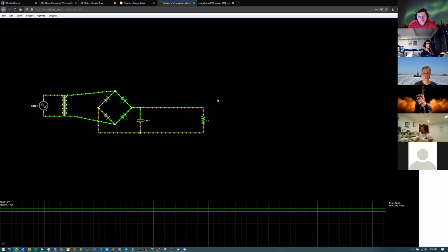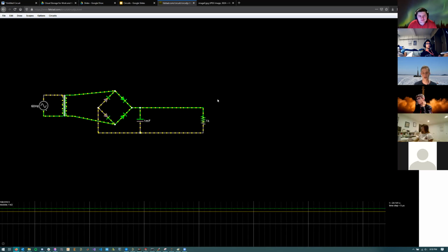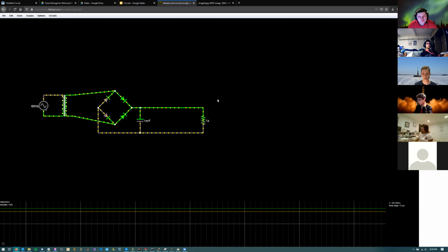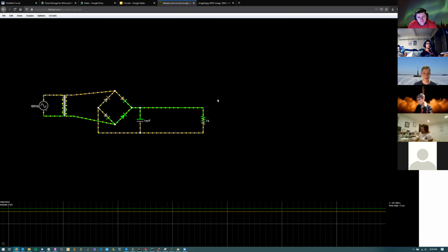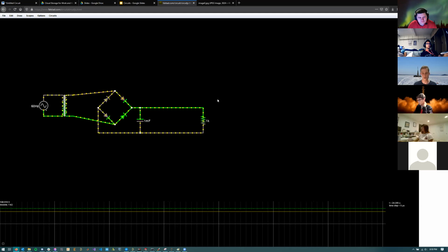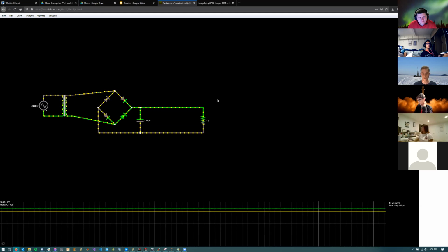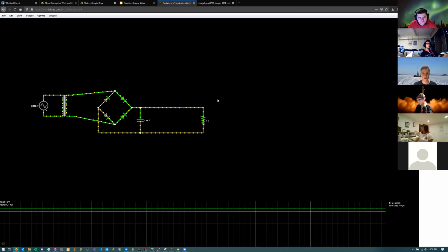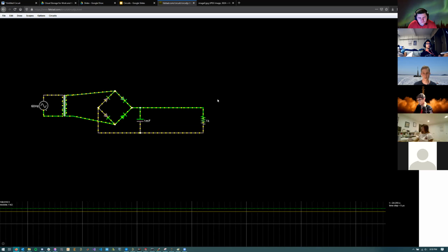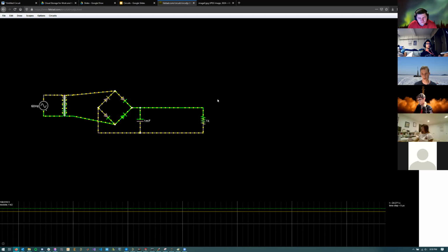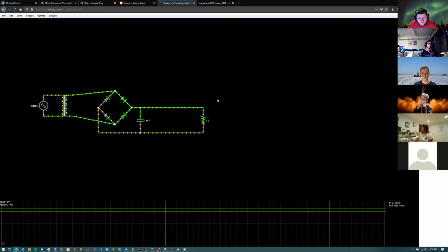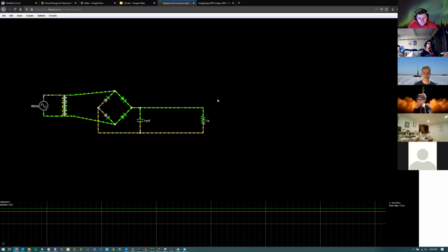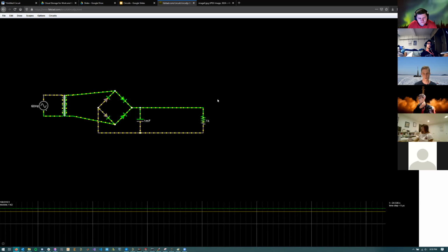So the reason why we use capacitors in DC circuits and integrated circuit-based designs is, most commonly, to decrease the presence of AC voltage, which can mess up the internal circuitry of our integrated circuits, so our processors. We call those bypass or decoupling capacitors. I will discuss those with the Arduino.